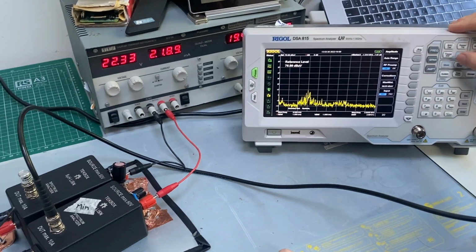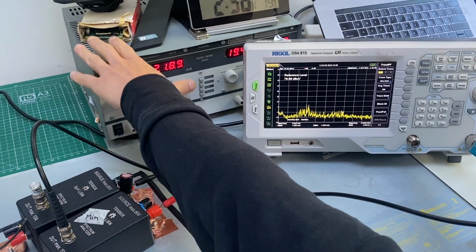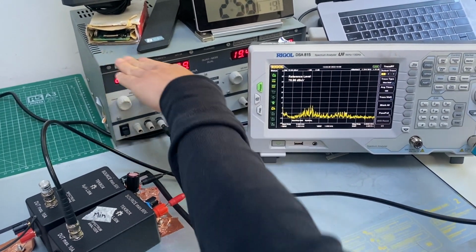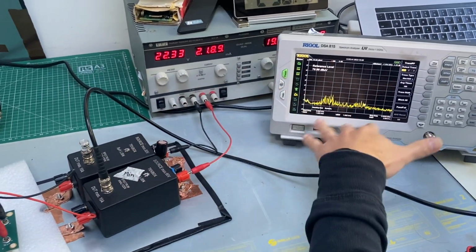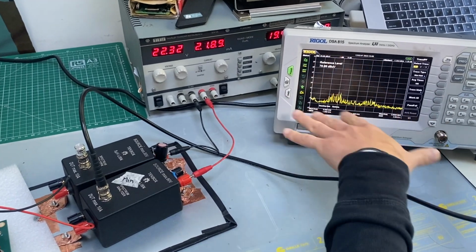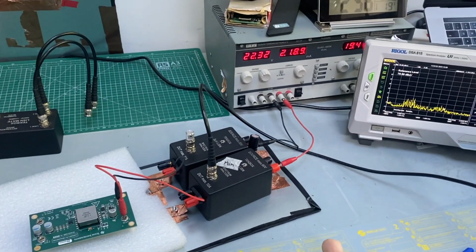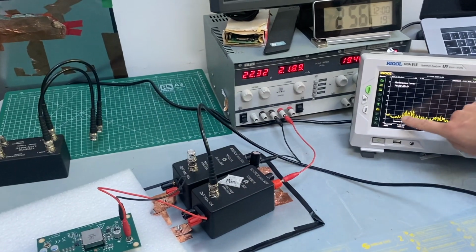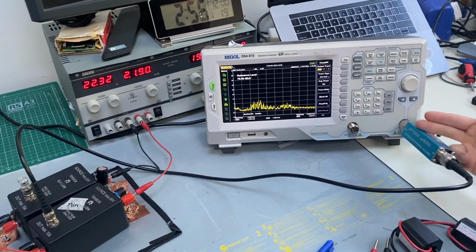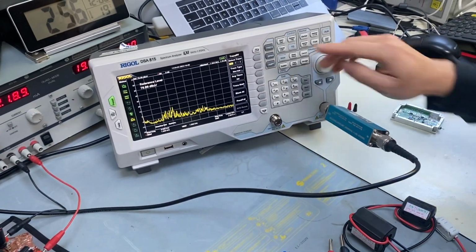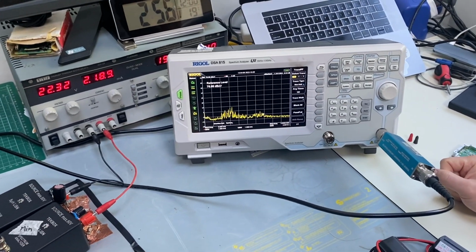This noise is what we call the ambient noise. This noise comes directly from the power supply unit. So if we measure the DUT without knowing this information, it could be misleading, because this noise doesn't come from the DUT, but rather from the power supply unit, right? If I max hold this, you can see this is the noise coming from the power supply unit. Bear in mind, I already have a high-pass filter here, so if I didn't have the high-pass filter, this noise level would be 10 dB higher. So quite a high level of ambient noise here, right?